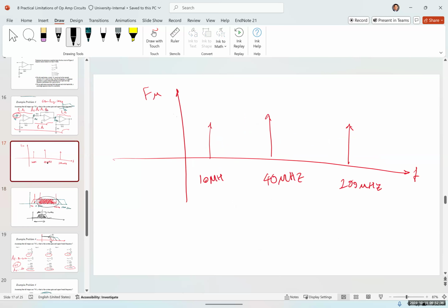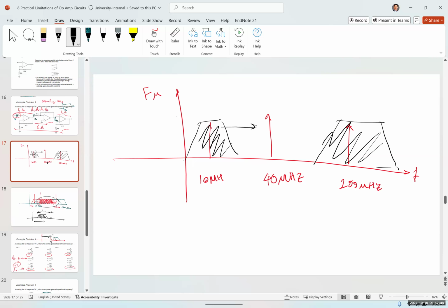When we want to pick up a frequency, for example, 10 megahertz, we will first put our filter here. We will pick this and eliminate everything else. Then we will move our filter, for example, to the 3rd station. So when you're moving that knob, you're moving a resistor, changing a potentiometer, for example, or a variable capacitor. And by that, you're changing the upper and the lower cutoff frequency, you're shifting your filter. And this is called a bandpass filter.